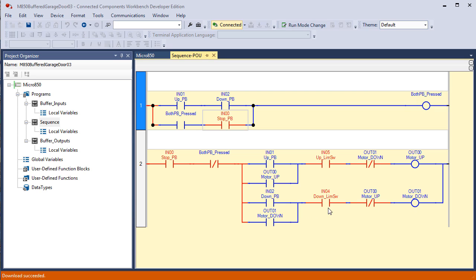And if you put it in here, then you are making the rung a little fatter or wider, so to speak. What I had you do, lab project manual, and you could put it in here. Remember, the only reason we're not putting it directly in here, and it's not really a bad idea, because you could put it right here saying if it's not already down and the photo eye is not blocked, then turn on the motor. That might be the most obvious place to put it, in series with these two right here. However, I'm going to go offline and show you where I put it in the manual.